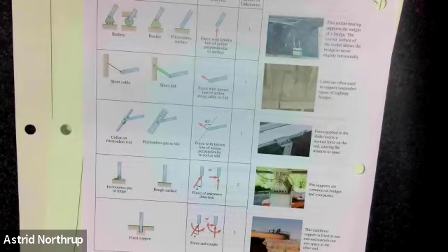So that means that the reaction forces act upward if the force is straight downward. And the distribution of that weight, the force in each leg, can be equal if the weight is equally distributed, or if we place a weight really heavily right here, this leg is going to bear more than the other 3 legs. And using summation of forces, summation of moments in all 3 coordinate directions, we can determine what those are.